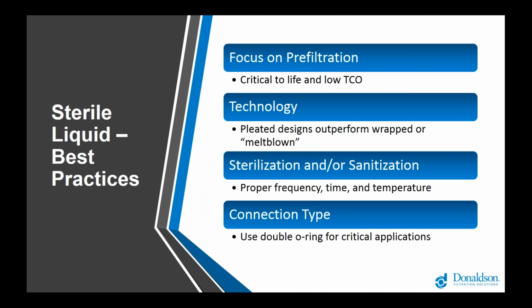And whenever it's an application that really matters and the filtration is of critical importance, you really need to use the double O-ring design. A lot of the same medias and same models can be had in either connection, and the double open end tends to be quite popular because they're oftentimes low cost comparatively with the double O-ring designs. But the double O-rings are just much, much better and more effective at producing a true seal in an application